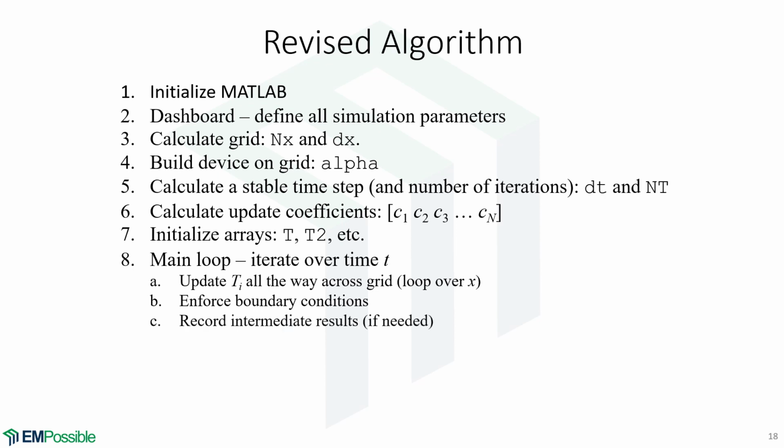We might record intermediate results if we want to. We might want to visualize the intermediate results. I always do this when I'm doing time domain simulations. I don't want to wait till the end to look at things because what if something's going wrong? What if my simulation takes a week? I don't want to wait a week if I can tell something's going wrong in the first hour or two. So I always like to visualize my results, intermediate results.